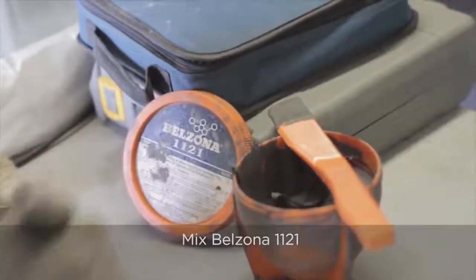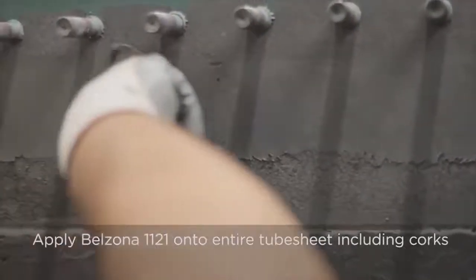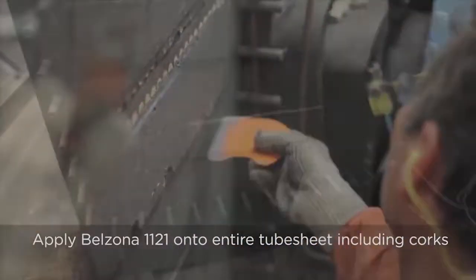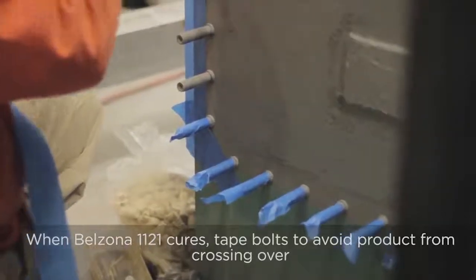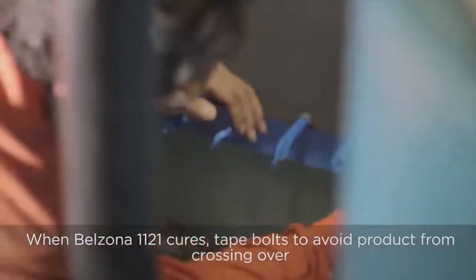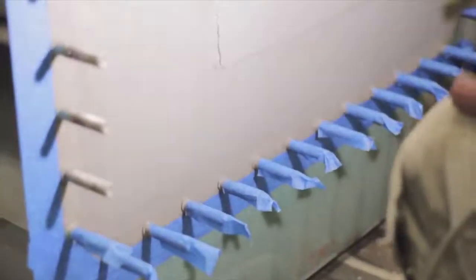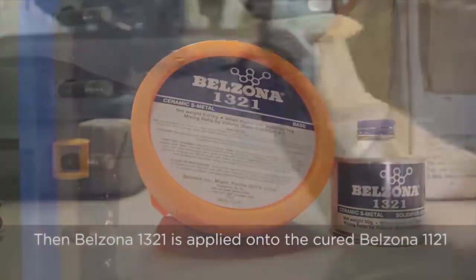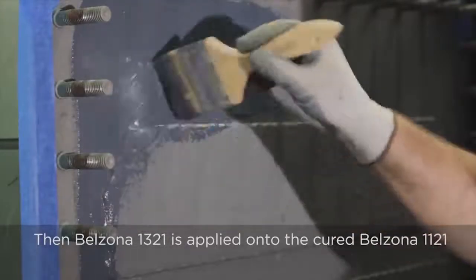In order to get this metal back up to a surface where we can apply a coating, you then mix up the epoxy paste grade, and he's just going to use a spatula and paste that onto the surface after the surface prep to rebuild it and get a nice flush finish to the application. After the Belzona paste grade is cured, you then remove all of the corks, to avoid the product going down the tubes, replace them if necessary, and then you can apply the Belzona 1321 or other ceramic-based coating directly on top of the Belzona paste grade, as long as you're still within that overcoating window.